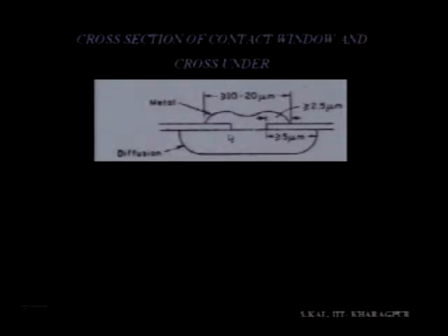You have to ensure that the window is just at the middle of this diffused layer. If this window is somewhere from this region to this region, in that case, say if it is an N diffused region and this region is P, then P and N are all together connected in the contact, isn't it? And that may not be desired. So that's why in each contact window some tolerance is given, that is, this is in 5 micron technology, 5